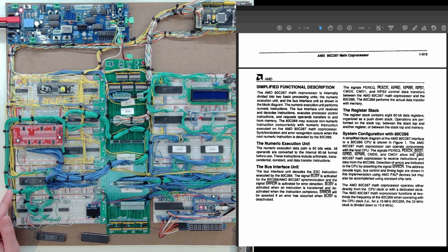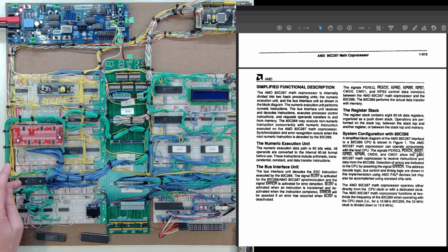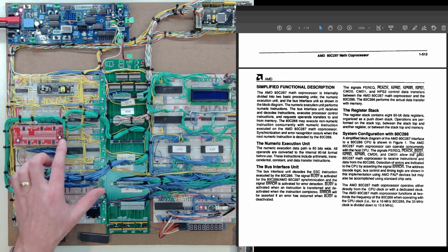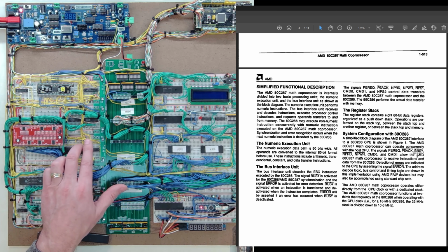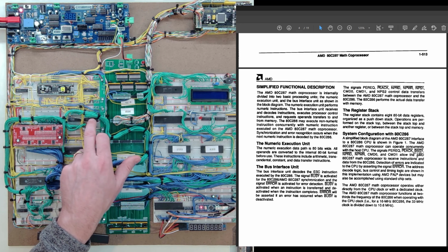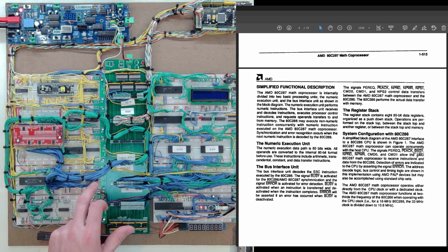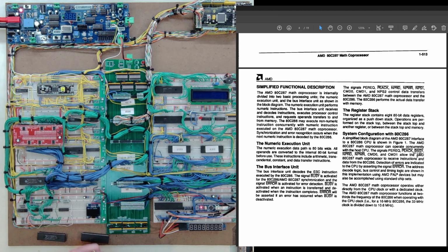But one thing I noticed when I was going through and testing, well, maybe let me back up. One thing I did notice, before I get to what I ultimately changed that I think fixed it, I did look at the outputs of my data transceivers, because I wanted to make sure they were showing the right voltages. And I was seeing 5 volts on one side and 4 point something on the other, and I thought that was a little weird.